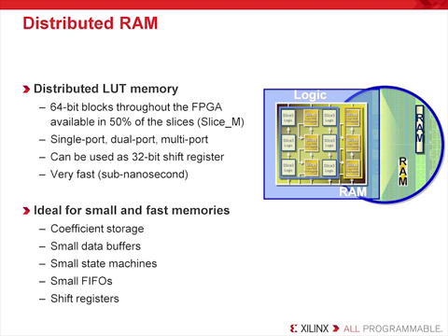In general, you should target the block RAM over the distributed RAM. The reason is that block RAM is a lot bigger and dedicated in the silicon. You can always use another LUT for combinatorial logic, but if we fail to use a dedicated resource, such as the block RAM, it'll be wasted.